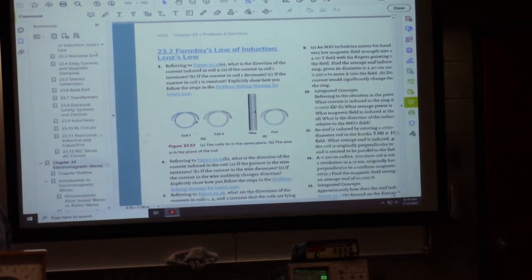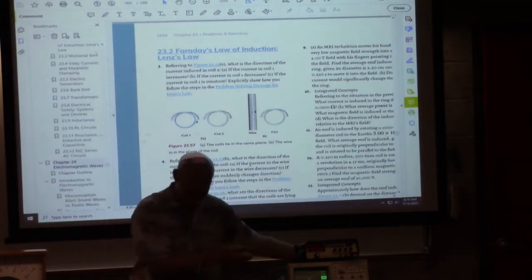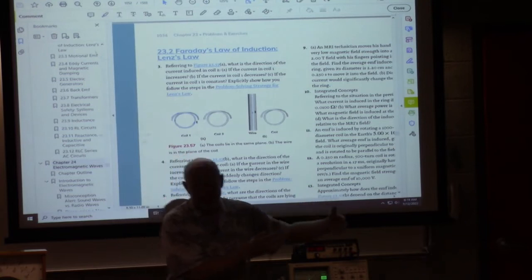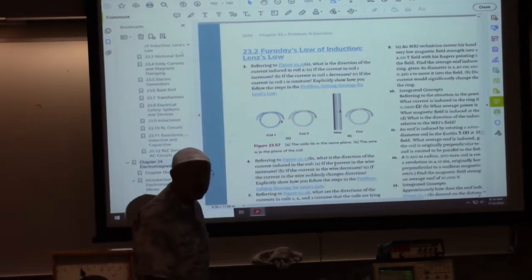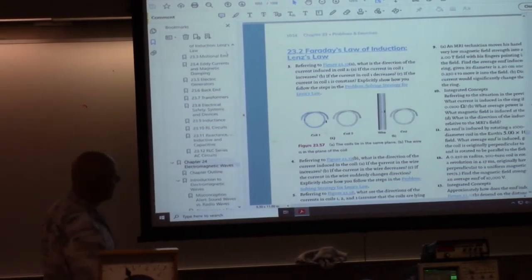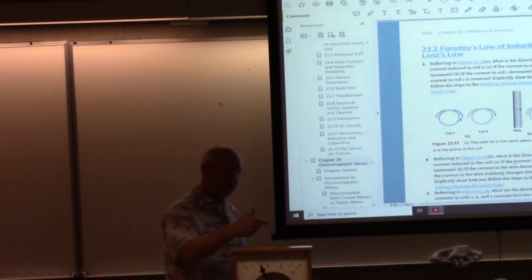Well, good, and I'll say it again because you're nailing it right on the spot, that in order to see this, you got to see which way is the flux from the primary, and then you got to see which way it is changing, either an increase or a decrease, before you can then figure out which way the flux is supposed to be in the secondary, which then eventually gets you to the direction the current is supposed to be in the secondary. So there's quite a few steps there. And you have to remember it opposes the change, it doesn't oppose the flux.